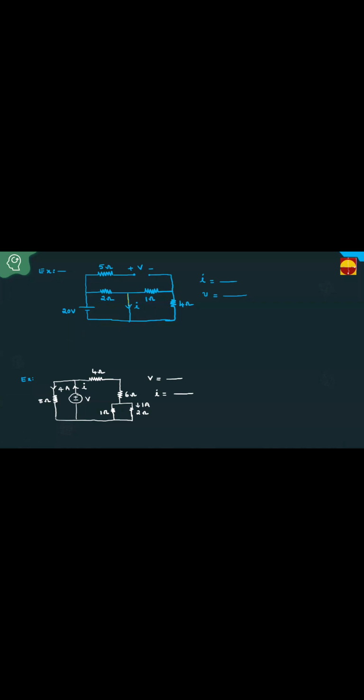This is short circuit now. Once it is short circuit, there is no current in this resistance. This is completely open. Then the current is flowing here. It is short circuited, current will flow like this. There is no current means it is open circuit. Once it is open circuit, there is no current here. Then current is flowing here. 20 volts, 2 ohms, 20 by 2.